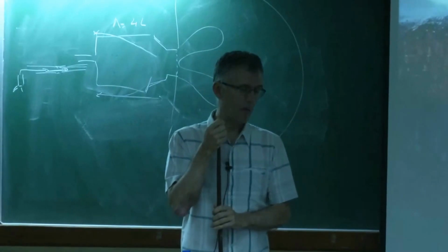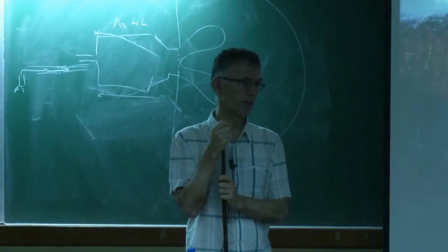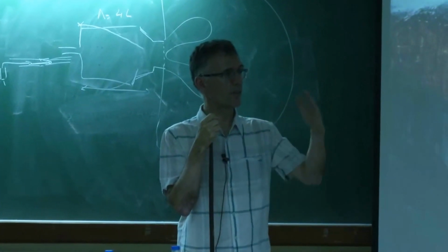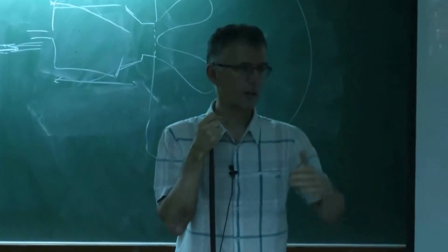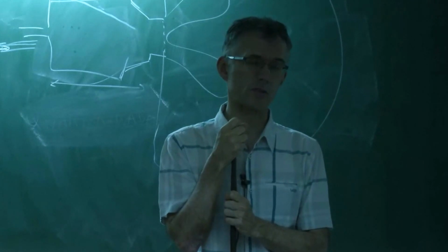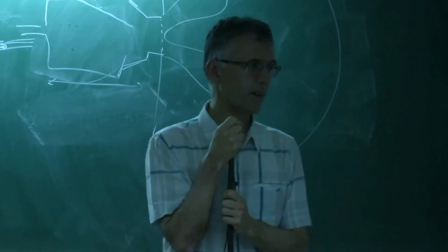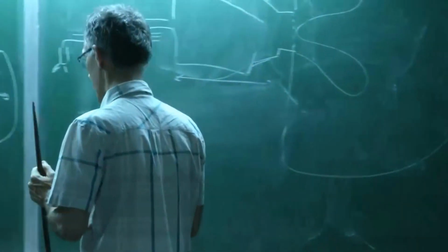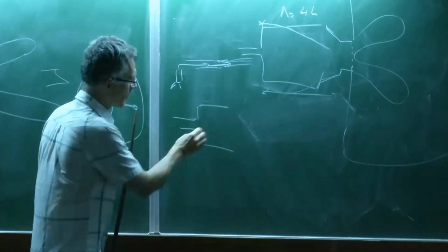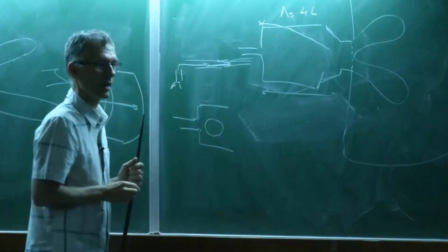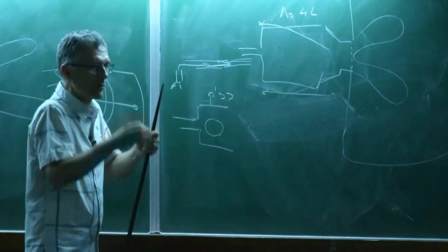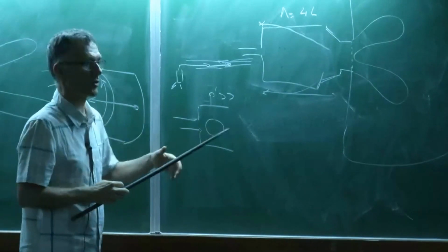Well, the amplitude depends on a lot of things. It depends on the quality of the scheme, of the numerical method. If the method is dissipative, you get less amplitude because it's damped. And also the amplitude very often in an experiment depends on things that you don't want to discuss. Leaks, for example. In my experiments, when I was doing my PhD, I had very small leaks on the quartz window here. And if you have leaks in a region where p prime is large, then p prime is a little bit damped, and so in the experiment you get to another level.